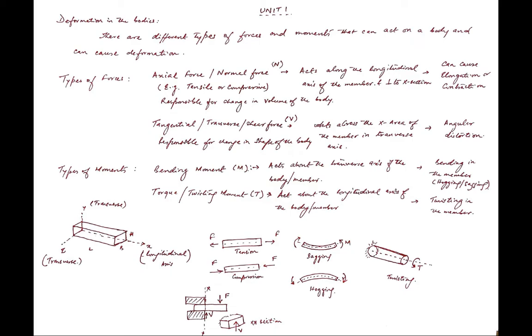Okay, yes sir. Mass moment of inertia is different, second moment of area is different. Second moment of area is a geometrical property of a section, and mass moment of inertia is, you can say, the natural property of the material. Okay, because mass is also associated with it, and it will define the homogeneity of the material, how homogeneous the material is, and the inertial properties of the material. Okay, so the second moment of area, in general terms, in books also you will see it called only moment of inertia, so don't get confused with that.